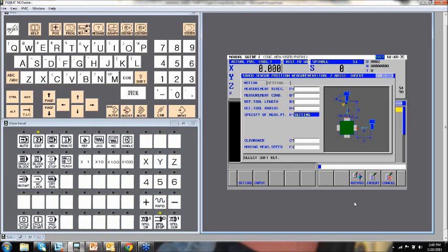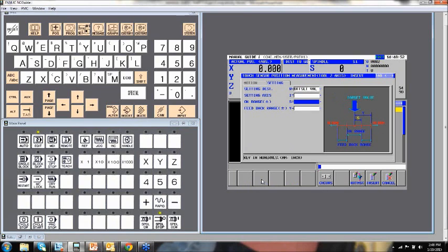And then you can either be setting, where it does put something in a variable, or to where it inputs it directly into one of your offsets. And then the setting destination, a reference value or an offset. Okay? And then you tell it which axes, and then the OK range.